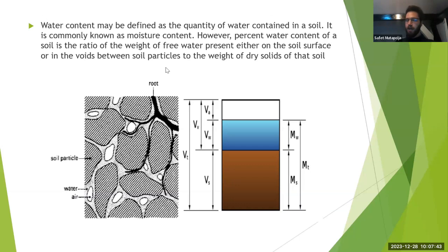There are two types of water inside of soil and rocks. Usually with rock you can have water that is trapped in the crystals. So using this method, that water is not going to escape. It's going to stay there, because you're going to need to reach a higher temperature to get rid of the crystalline water.